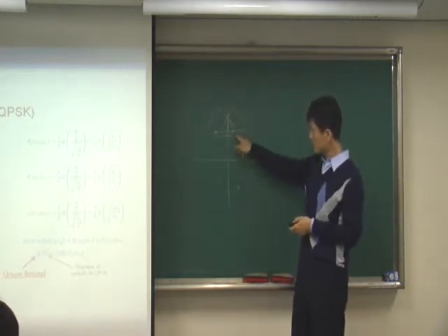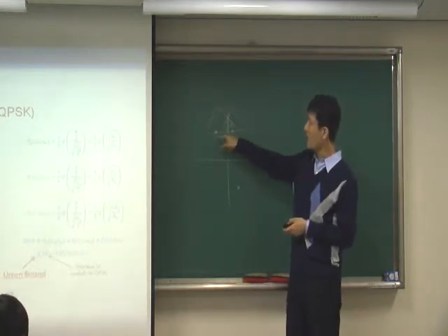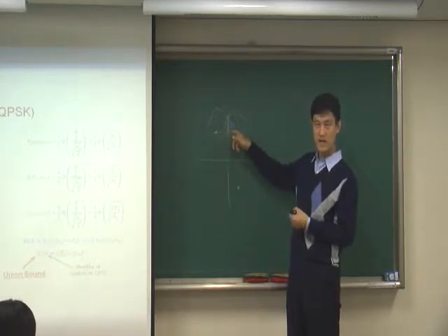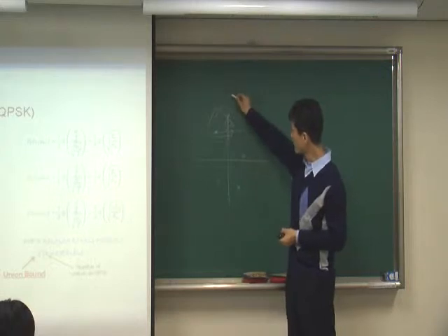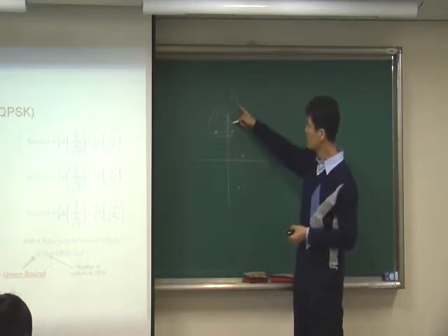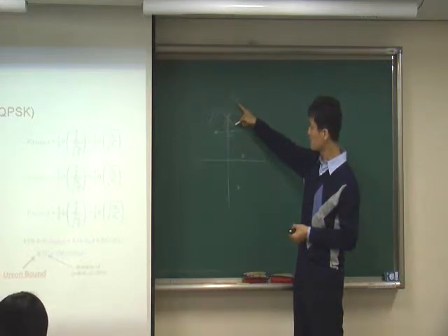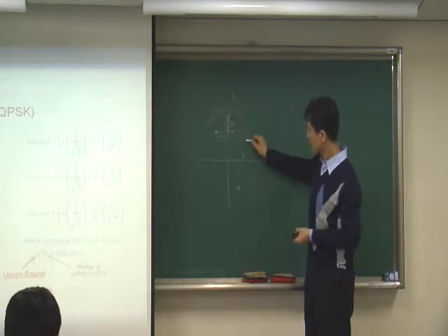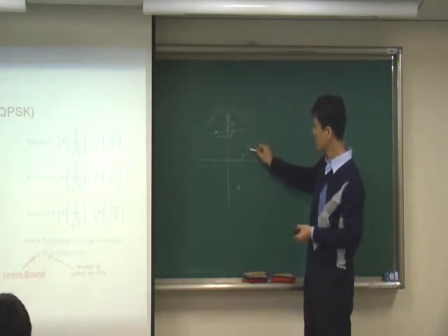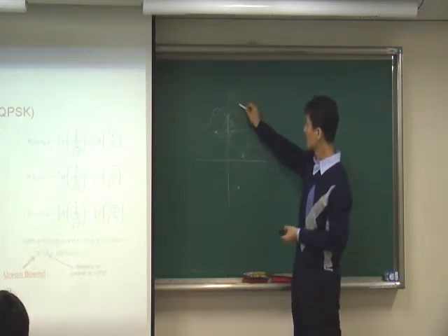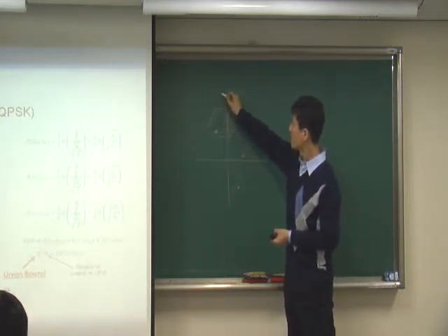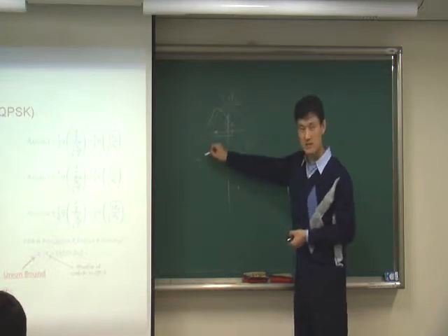So if you pick just one case with the highest bit error rate, and let's say that error rate is P1. This is the bit error rate of case 1. And this case, probably you have the bit error rate of case 2, but you ignore all these things. You only consider this one, and you multiply 5, because there are 5 different cases.